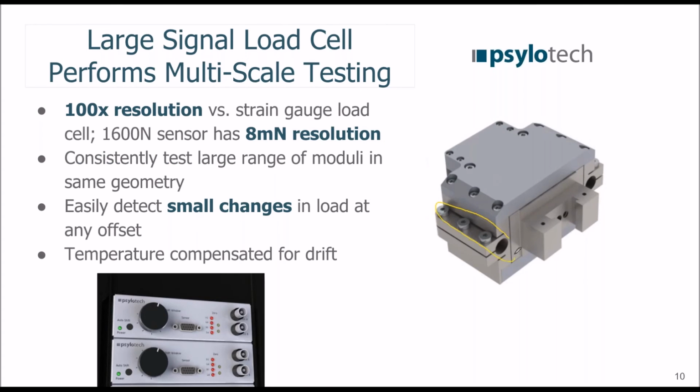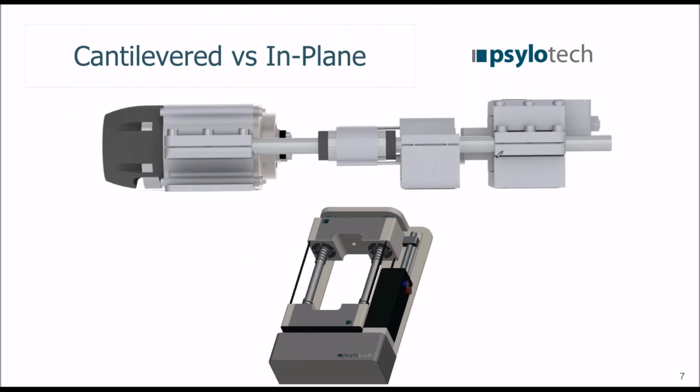So we have this rail insert here, and you can see that these 3 bolts on each side are all that clamps the load cell on, and then there's a connector on the back, like a D-sub miniature connector that's just not pictured here. And all you'd have to do is unscrew the connector and pull off the load cell there. Let me see if I find another picture. So you see here, this is the load cell, and it just slides right off of these shafts here. So it's a relatively easy thing to swap out.